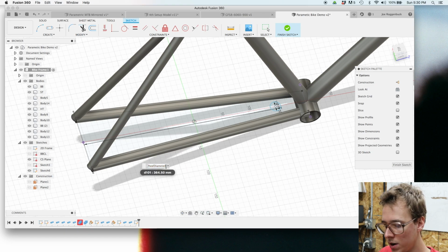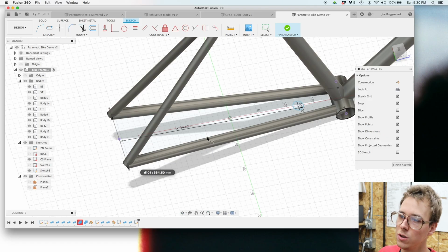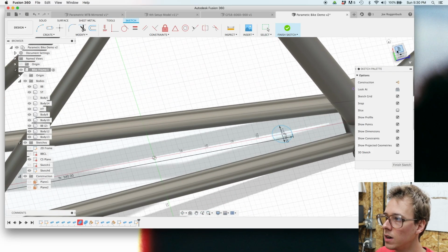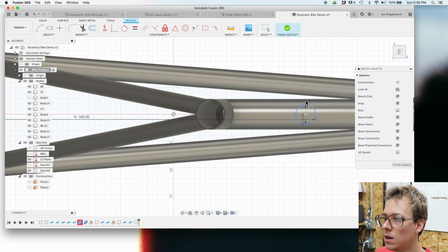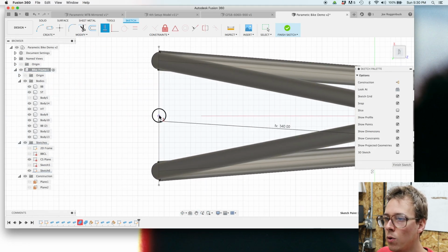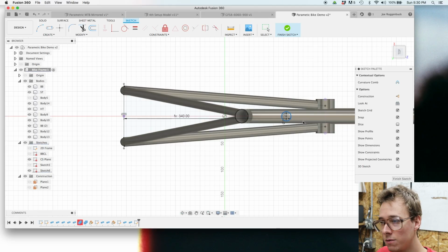I want that, but I want to divide it by 2 to give us the radius. And you can do that in Fusion in the dialog boxes where you're typing in values. You can do math equation statements. And now if I want to make it horizontal with that point, which I've done, and now it is fully black and defined. It's not going anywhere. That's pretty awesome.